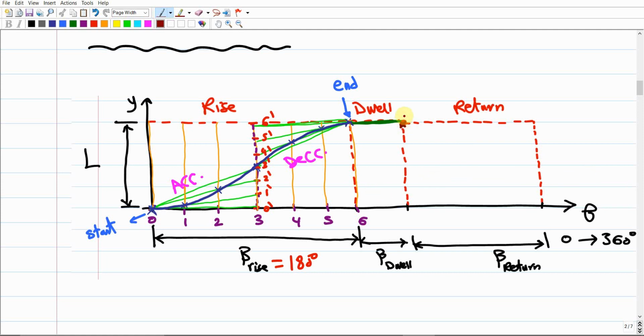So starting from here, why do we start from here? Because basically we're going to start from here. So this is going to be our 0 point. Then we're going to divide it into 4 divisions. If this angle is given to us as 120 degrees, and you divide 120 by 4, this gives us 30 degrees. It means you're just going to measure 1 centimeter, and another centimeter, the 3rd and the 4th. So this is going to be mark 1, mark 2, mark 3, and mark number 4, right?